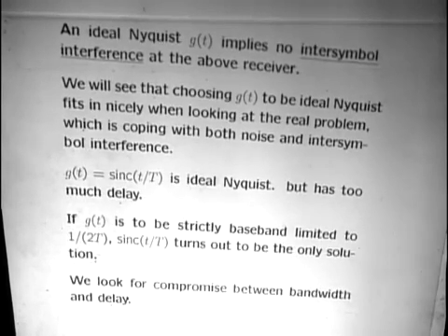In other words, if you want something with better delay characteristics than the sinc function, your only way of doing it is spilling out into slightly higher frequencies.